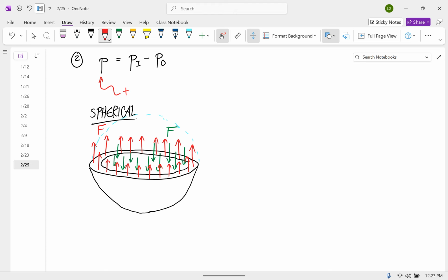So remember that what pressure does is it applies a perpendicular force to any surface. And so what we have done is we have chopped this off horizontally so that the surface is horizontal. And that means that the pressure only acts the way we've cut it.